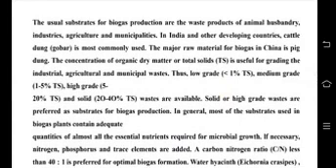The concentration of organic dry matter or total solids is useful for grading the industrial, agricultural, and municipal waste. Thus, low grade is less than 1% total solids, medium grade 1 to 5% total solids, high grade 5 to 20% total solids, and solid wastes 20 to 40% total solids are available. Solid or high grade wastes are preferred as substrates for biogas production.